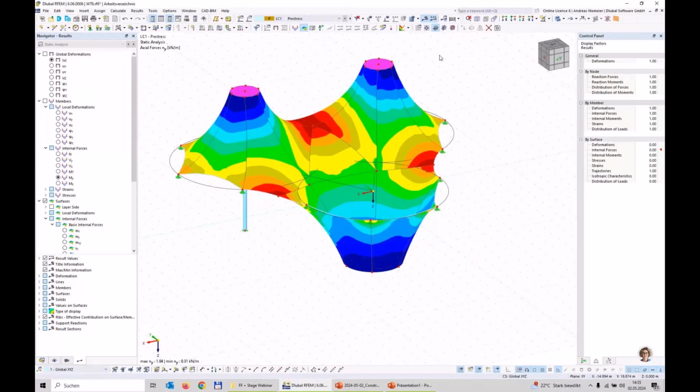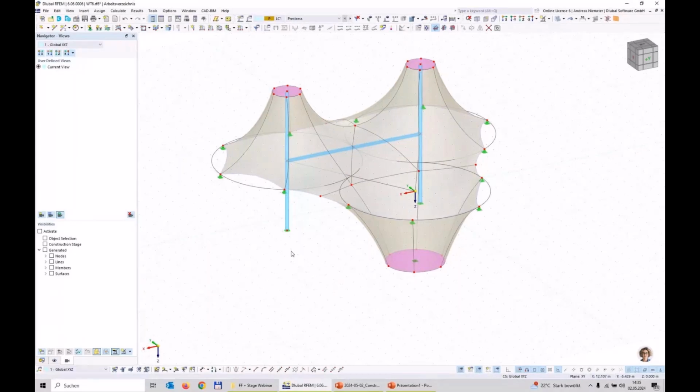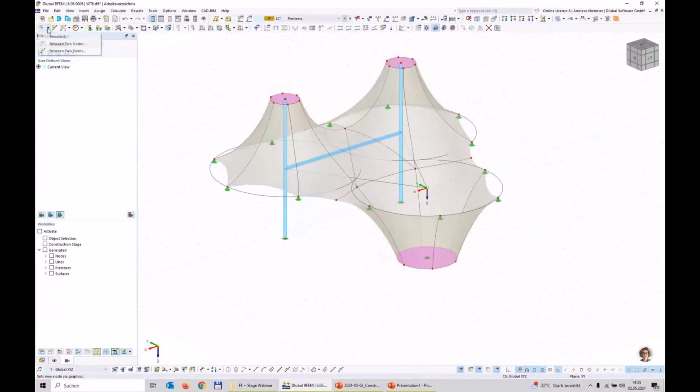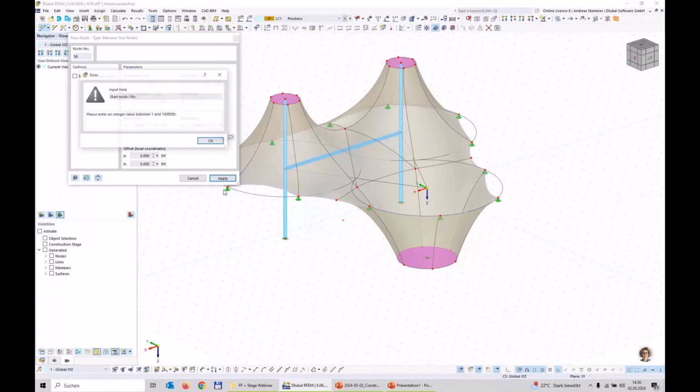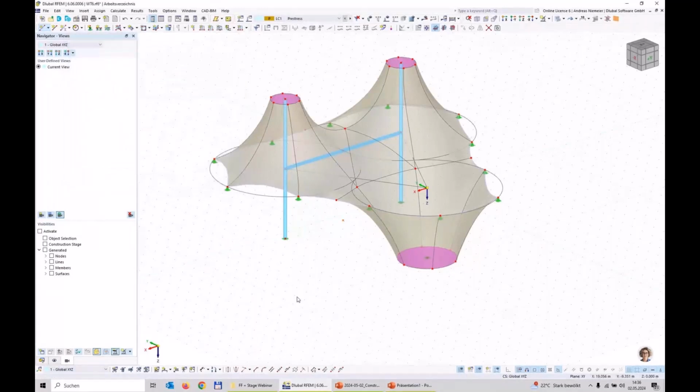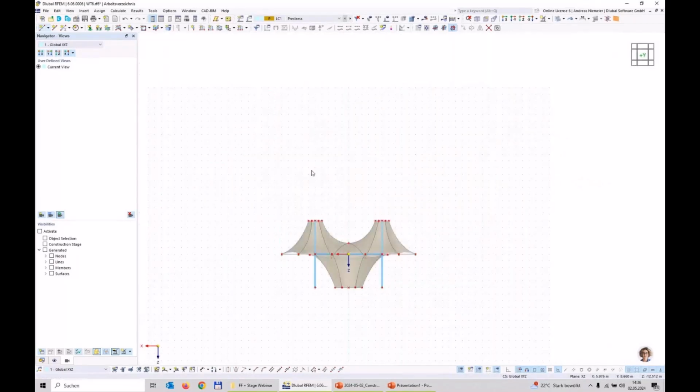So let's do this. So let's make here, replace this frame or draw additional. So I draw here node between lines, pick these two nodes, confirm, apply, and now use here this grid point plane and place it here inside this frame. Now we can watch in Y direction, and let's say we can draw here such an arc, for example, like you saw in the picture here.